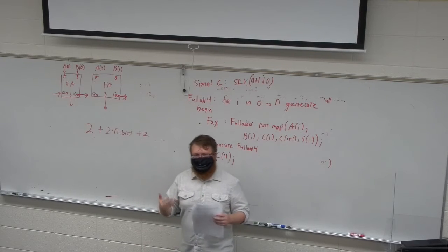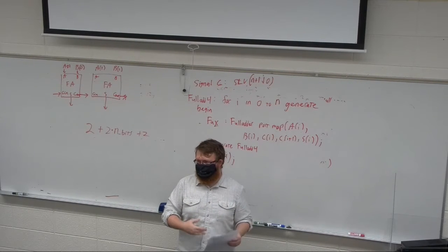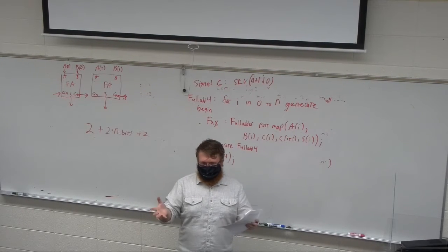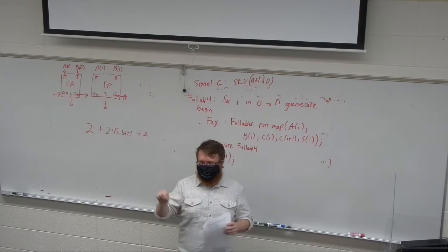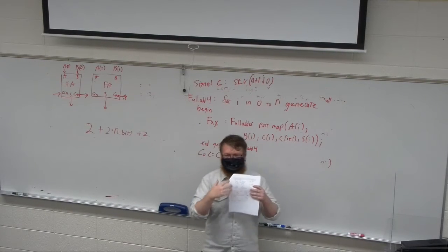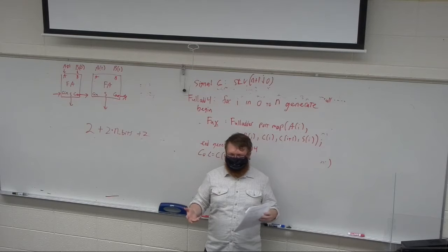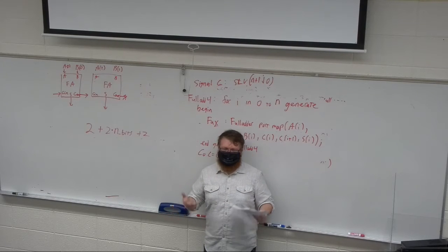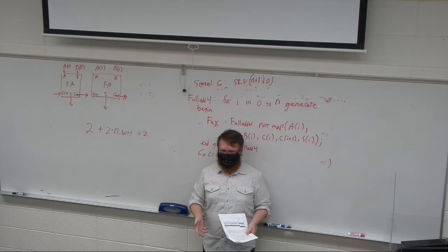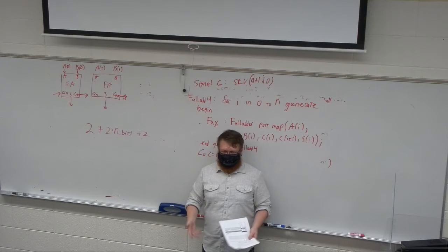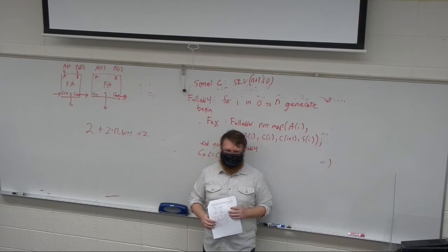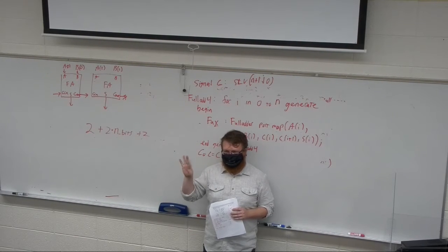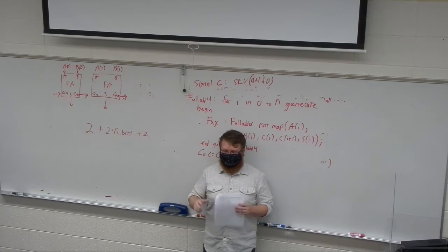The important thing to understand is that when you declare an integer, your digital logic will create it as a 2's complement. It can't have a no bits answer. That's the most wrong one that I saw. It's no bits? Well, no, it does have bits. Numbers are universally stored as 2's complement. So it throws 1 bit as the sign, and then it needs 4 bits in order to be able to count up to 16. So it's 5 bits. We'll see how we create that.